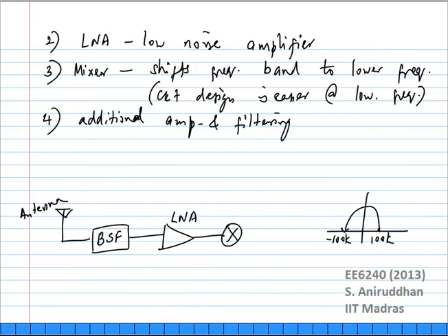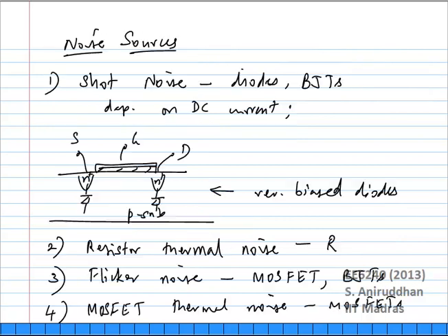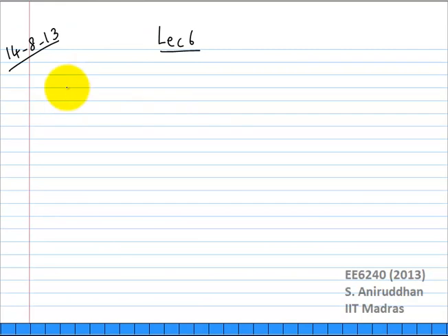And we started off with looking at the RX system. So we said from the antenna you will first need an LNA. Okay? What does a low noise amplifier do? It adds very little noise while amplifying the signal. As simple as that. Right? An ideal amplifier would amplify it without adding any noise. So the signal to noise ratio at the input will be the same as the signal to noise ratio at the output. Okay? It will amplify the input noise as well as the input signal naturally.